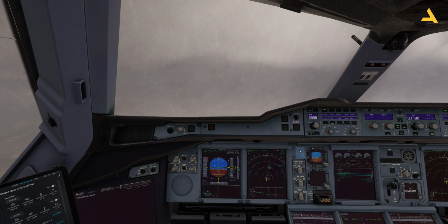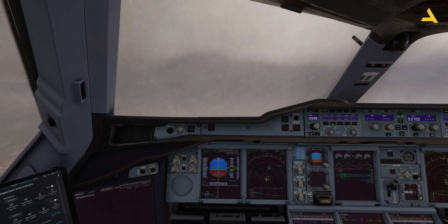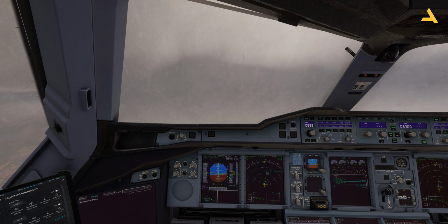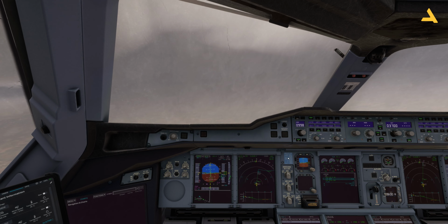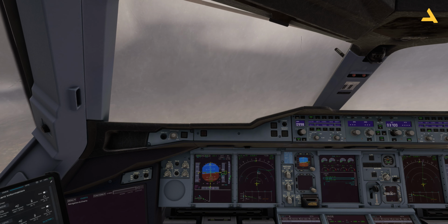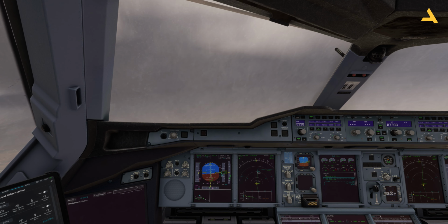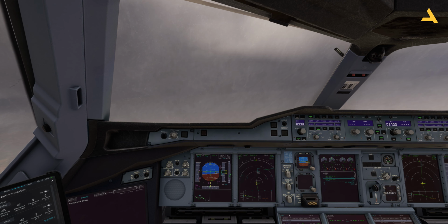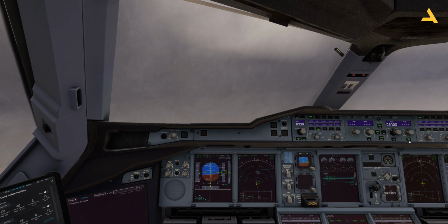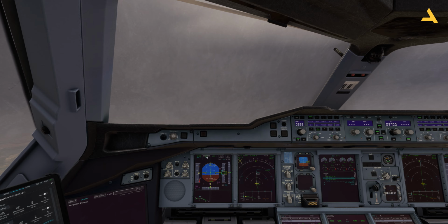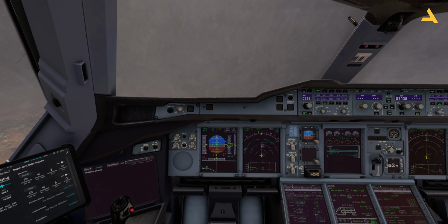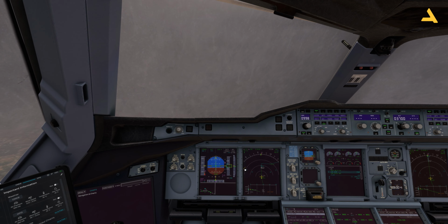That's it. I'm not going for the auto land. I tried it before when I was recording this video earlier. This auto land feature was not so good. So right now I'm not going to take the risk. Although once you activate approach, then you can activate autopilot and the plane auto lands. All you have to do is this, just like 30 feet above the ground or the runway. When you see flare over here on the FMA, you bring the thrust levers to idle, and then once the plane touches the runway, you activate the reverse thrust.